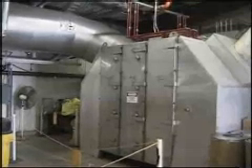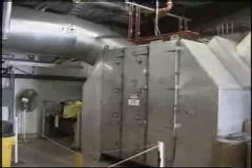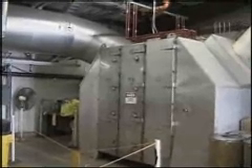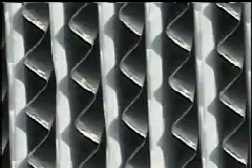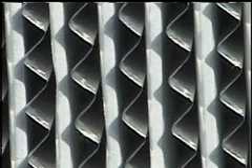Another single-use particle collector is the high-efficiency particulate air filter, or HEPA filter. HEPA filters are used for the high-efficiency removal of submicron particulate matter from a gas stream that has a low contaminant concentration. The filtering media is a continuous sheet of fiberglass or cellulose paper that is wrapped in an S pattern across corrugated metal or ceramic support strips.